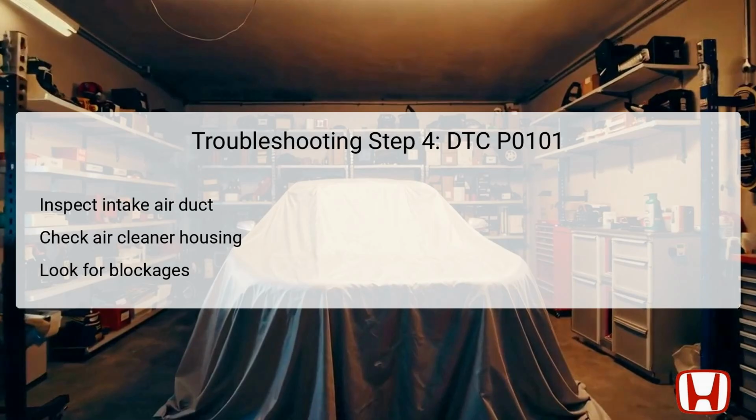Next, assess the air cleaner housing, ensuring that the air filter is clean and properly installed. Blockages in either component can lead to an incorrect volume of air entering the engine, throwing off the air-fuel mixture and potentially leading to the MAF sensor triggering a fault code. Normal conditions at these points are critical for the effective operation of the entire intake system and for the car to function optimally.